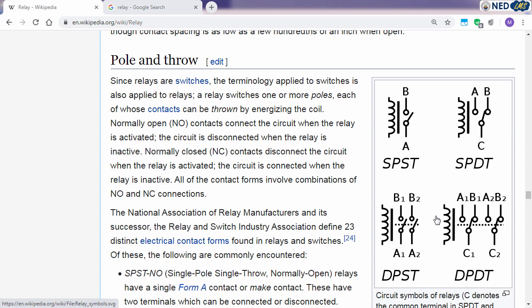Relays come in an electromechanical variety. There are also solid state relays, which are essentially transistor based. It depends on what the application is, and usually if you are using DC relays, always use a diode in parallel with the relay coil, so that if you turn off the supply, the diode is connected in this fashion. Let me draw it for you.